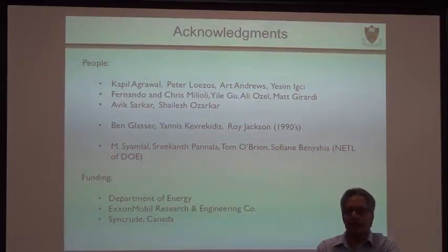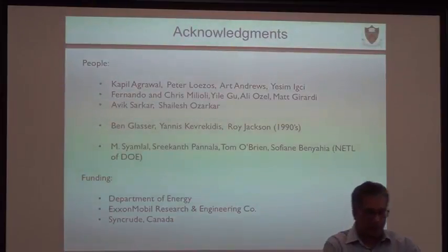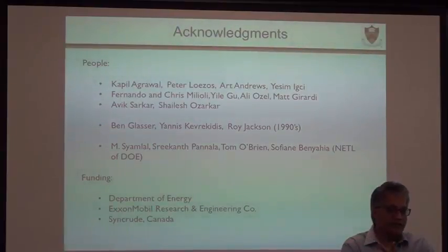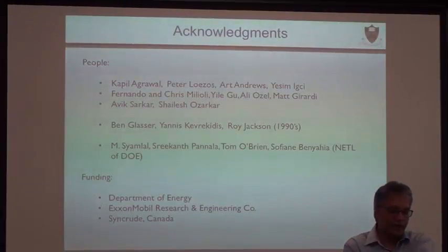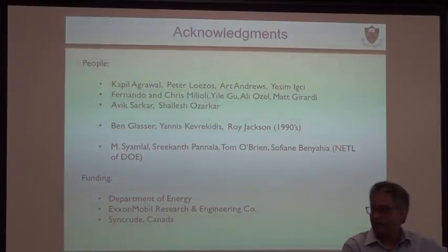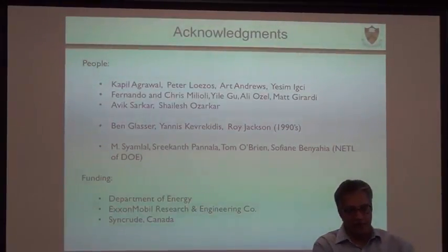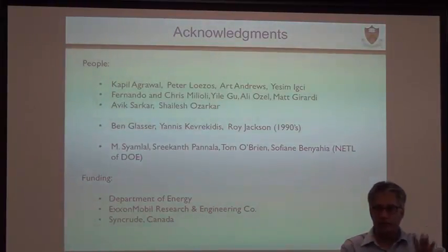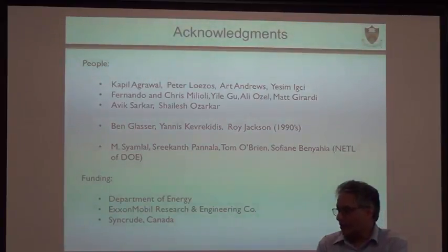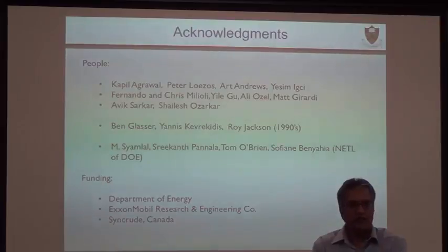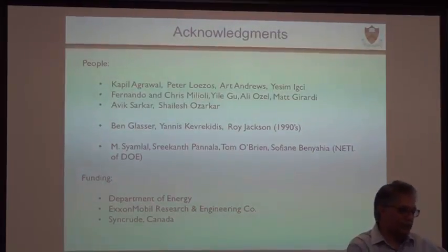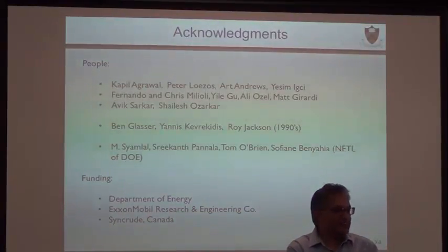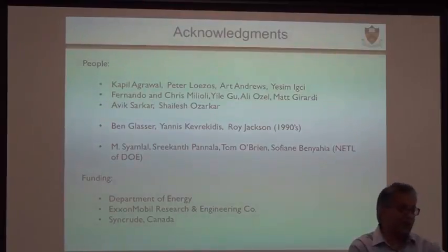Well, the first question is: what about volume averaging or time averaging? Now, if you look at single-phase turbulence, people talk about completely removing all the time dependence and Reynolds averaging all the way through, so you try to solve a steady state problem. Or you try to resolve the coarser scale flow structure in transient and model only the smaller scale flow structure in Lagrange simulation. We began by hoping for the first line, so we can average all of them out and come up with essentially a steady state coarse-graining model. I still would like to do that.